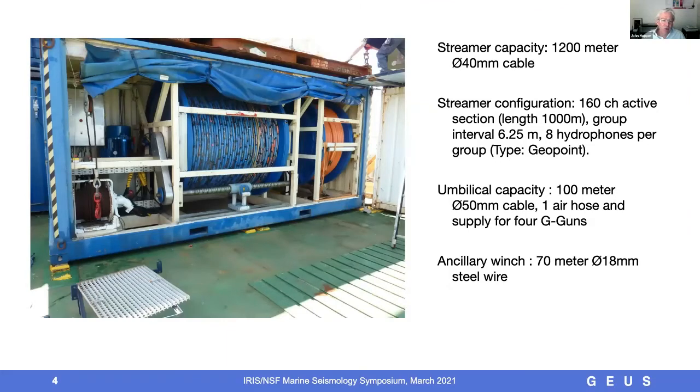This is the streamer winch. Again, it can hold up to 1,200 meters of streamer. We currently have a 160-channel active 1,000-meter streamer section, which is the largest that can be put on it. You can also see that there's some other equipment on here, including